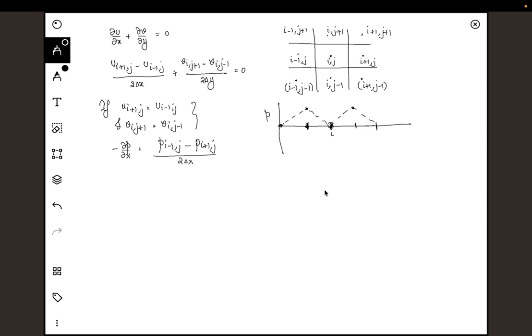So the idea to solve this is, I don't want both of them to be 0 at the same time. Instead of calculating gradients in this way, we will calculate the gradient for velocity at different points. If these are the pressure nodes, I will use the next ones to be the velocity nodes. Because I'm using different locations to compute the gradients, the chances of both of them being like this are small. If pressure is like this, then most likely velocity will also follow some similar pattern.